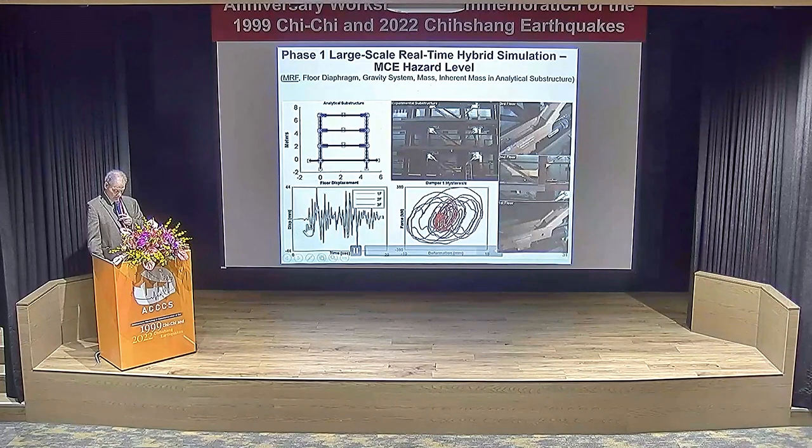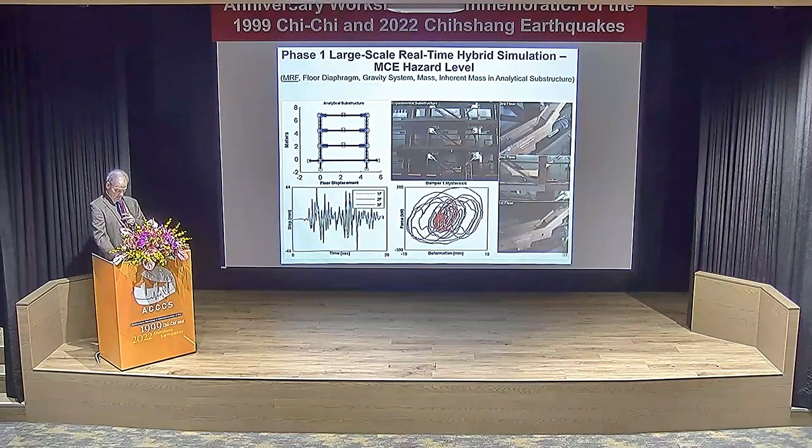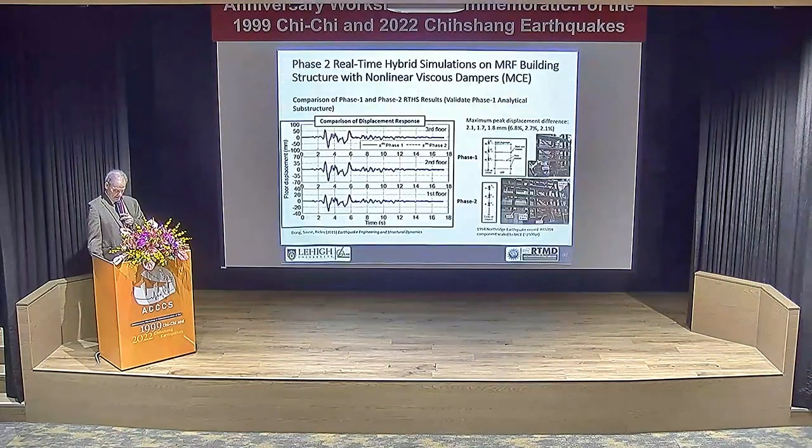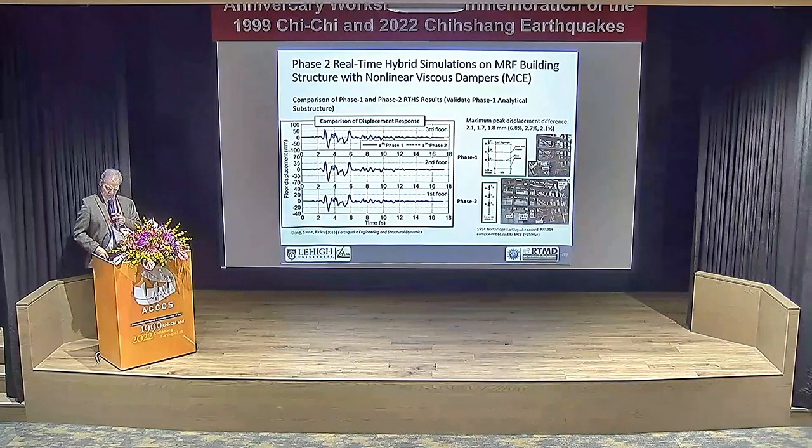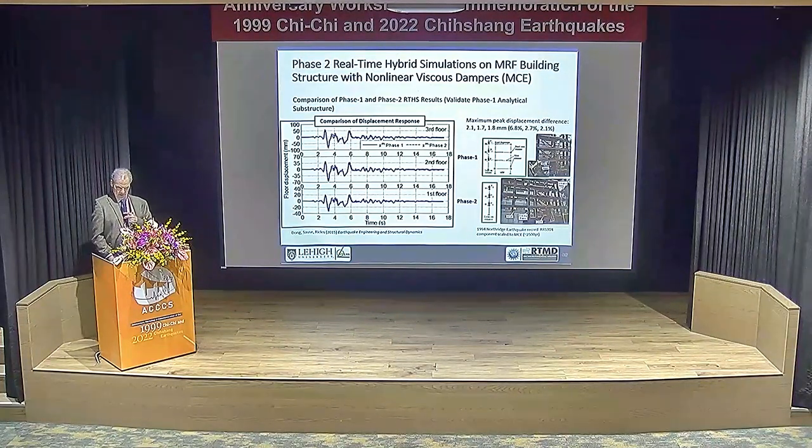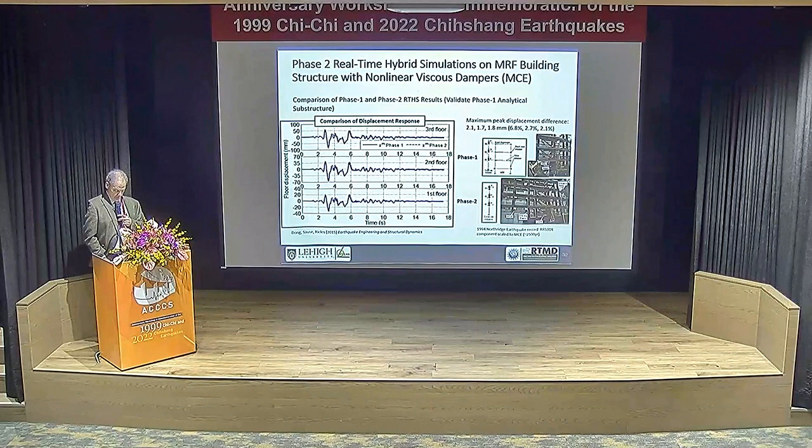This is the story drift. Story displacement, I'm sorry, versus floor. If we look at that, this is for the different earthquakes. I don't remember which is Chi-Chi, but you have it in the paper. This shows at the end of the simulation very minimal floor drift. This is for the design basis earthquake.